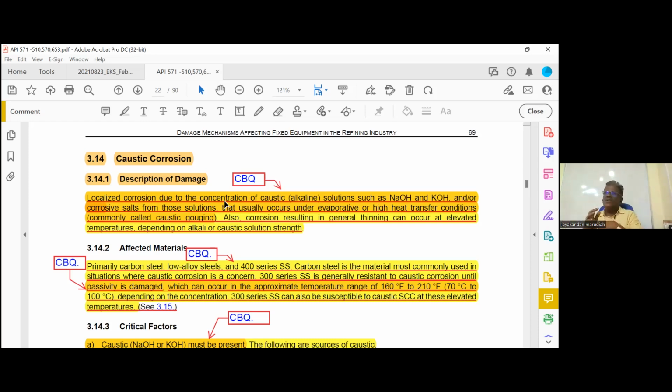So you should not allow it for a longer period. Heat it fast, cool it fast. You can relieve stress, but there may be one more problem: distortion will come. So we have to make corrective action so that it is not distorting because of the fast heating. If you want to do PWHT, practically yes, we can do. The only thing is the heating rate should be fast, which is usually slow. But a faster heating rate can sometimes result in distortion if it is not properly supported. So you have to make adequate support to avoid this. Okay, right.